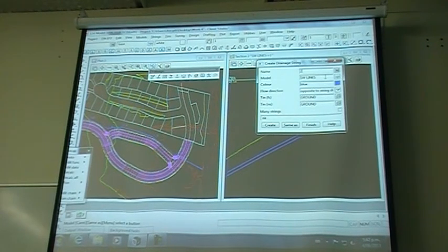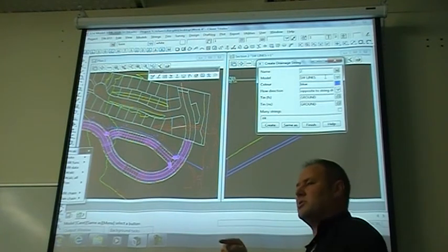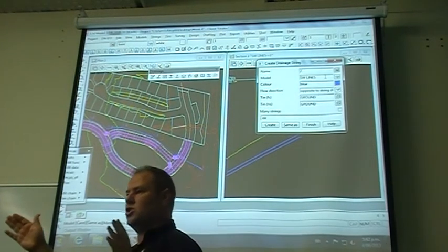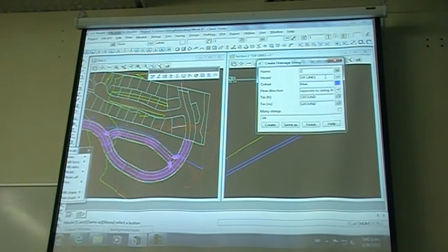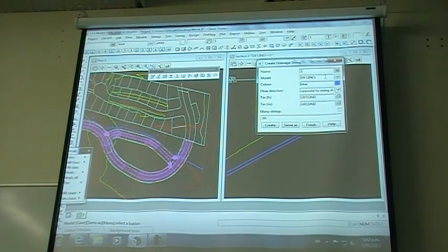I keep your naming convention simple. So all of our stormwater is going to be in one model, all of our wastewater in another. They have to have a unique name. When it comes to set pit names, if you've got 2 line 1s or 2 line 3s, it won't work. So they're all in stormwater lines and they're all individually named.